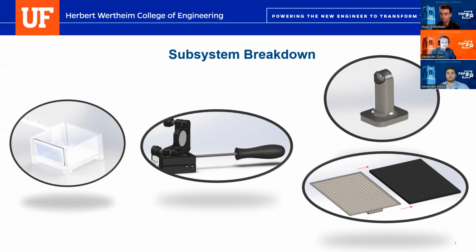The imaging chamber was identified as the subsystem responsible for not only keeping the zebrafish surrounded by water, but for also allowing accessibility both laterally and from the top of the chamber for laser entry and light projection. The imaging chamber is equipped with an Arduino pH sensor, able to provide accurate pH readings to determine when the water is out of the required 6.8 to 7.5 range. The wall containing the glass viewing window of the chamber is able to be removed from the body of the tank to allow the customer better access for sterilization. Both subsystems were designed to be optically transparent as specified by the customer.